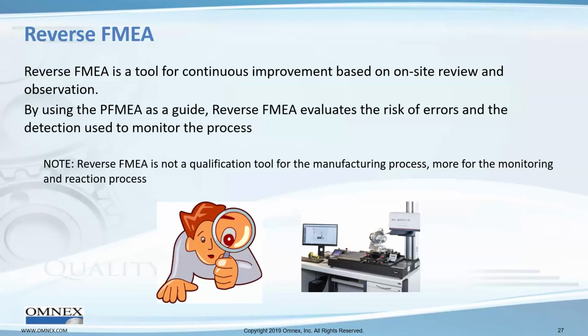Reverse FMEA again will push continuous improvement because we're reviewing what had been done in the past in the PFMEA and confirming that the documentation is correct, that the flow chart represents the process, that the PFMEA represents all of the failure modes that are crucial, and that the control plan is complete and it's being followed.